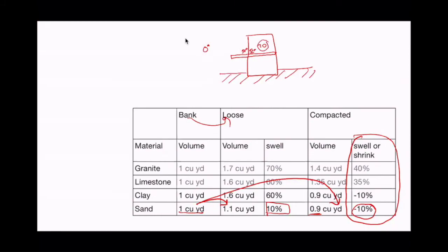And so your mechanical system is going to have to heat extra hard to cancel out that 52 degrees that's always coming in on that steel. And your feet are going to be adjacent to that floor, so through conduction it's going to be sucking heat out of your feet because it's a cold floor. And if you're standing here, for all the reasons we just talked about, the cold floor looks big relative to you.